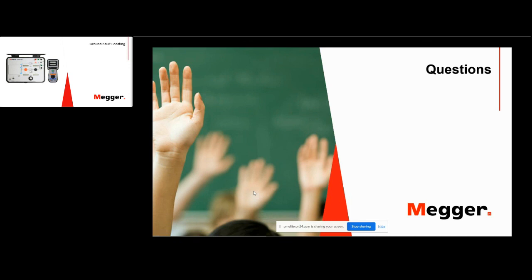And again, you're going to see the real current. You're only interested in that. You're not interested in the stray leakage capacitance current or the reactive current. So although it's easier to disconnect the ground fault monitor, it's not required, because you can measure the total out of the transmitter and then measure what's on that earth on the ground fault monitor. Then you can see the difference and know that's the value you're looking for.